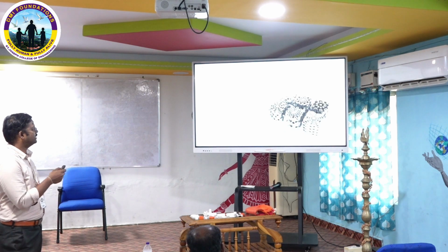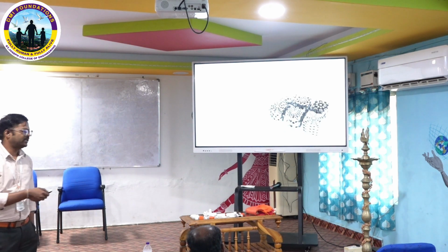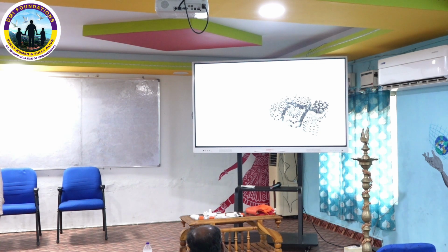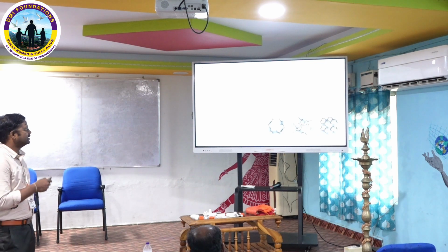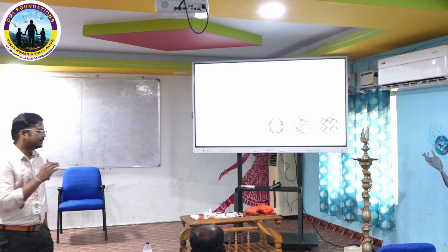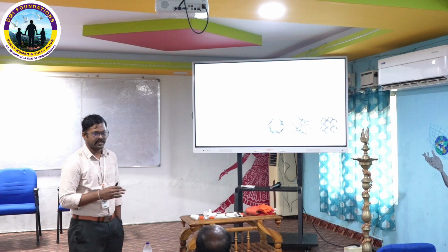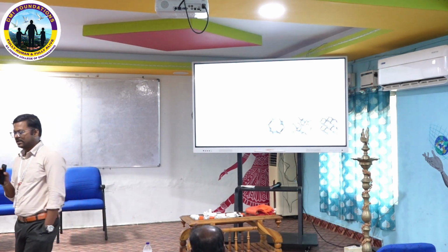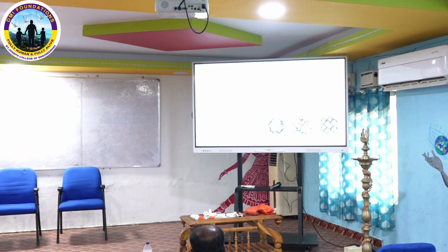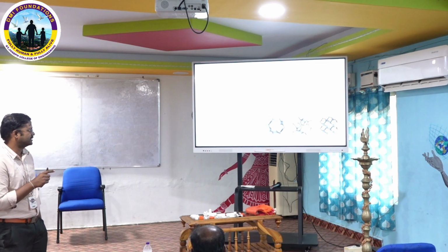First is selection of concept and objectives. Once you are clear on that, we go to the next one, which is called selection of unit cell. Based on the structure and deformation behavior, each and every unit cell is classified under mainly two categories. First is bending dominated, and the other is stretch dominated structure.